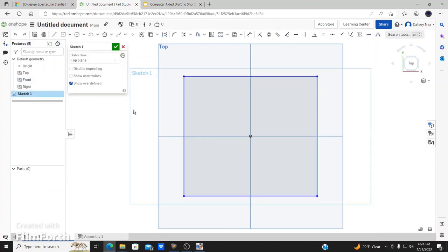Same thing with the dimensions. If I was gonna do dimensions over here, you can type D. Now you can make your dimensions right away, quick and easy. Rather than go over here on top, go down, go up top, back and forth, back and forth. That's gonna take a long time. But if you use D every now and then, this right here, good to go. Enter, right here, enter, and that's it.